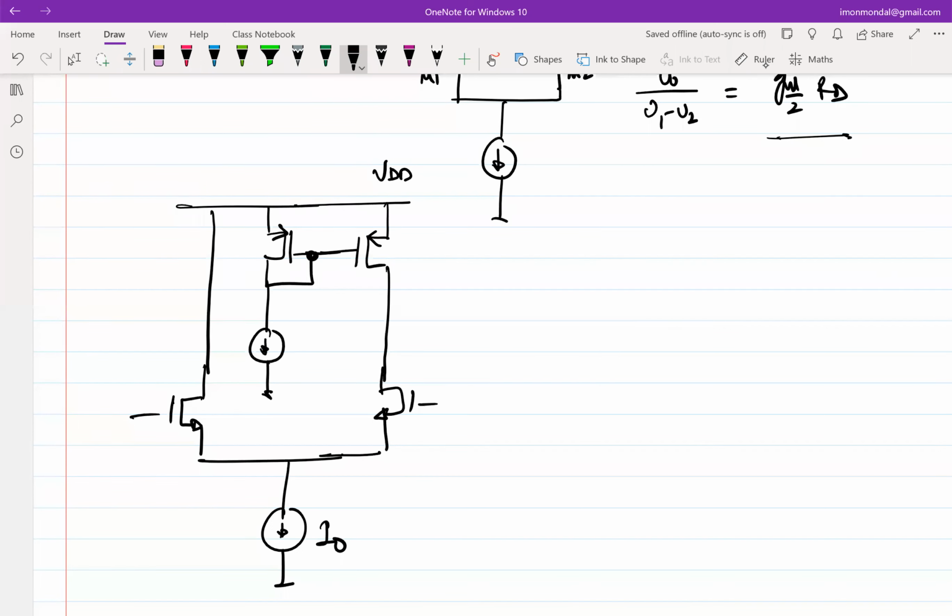So what is the quiescent? So let me mark everything properly. So let's say this is V1, this is V2. Okay. So let's assume the biasing is identical in both cases, because that's how the feedback loop will ensure the quiescent points to be. So this becomes, let's say, VCM plus, VCM plus. By CM, I mean common mode. That is one of the standard definitions. It's a common voltage between both terminals of the diff pair. So it's called common mode voltage. So we call it VCM.